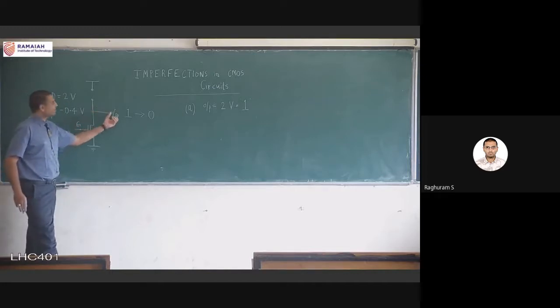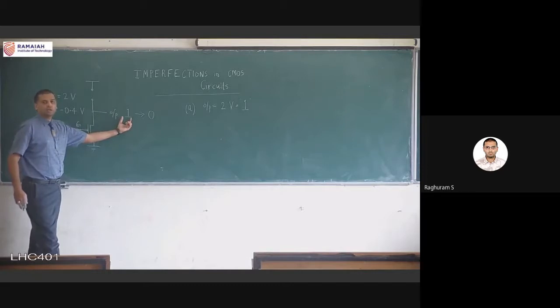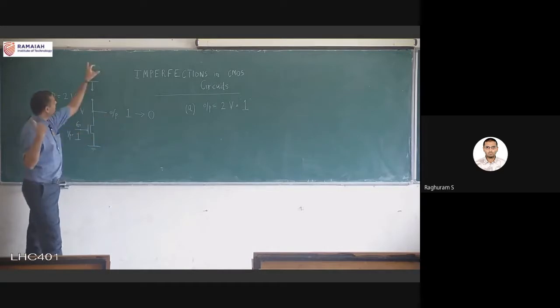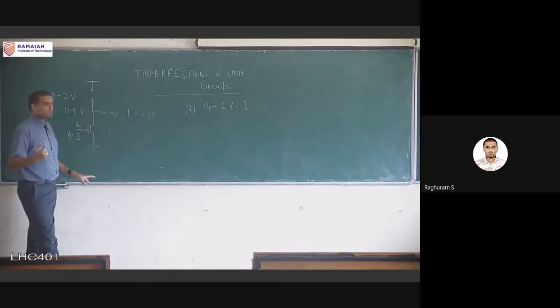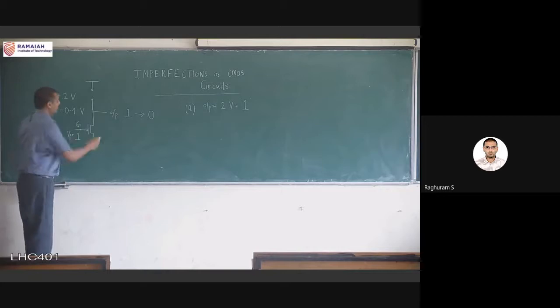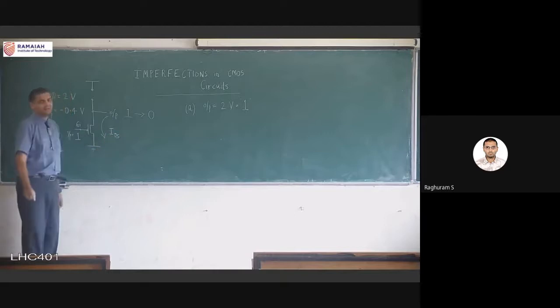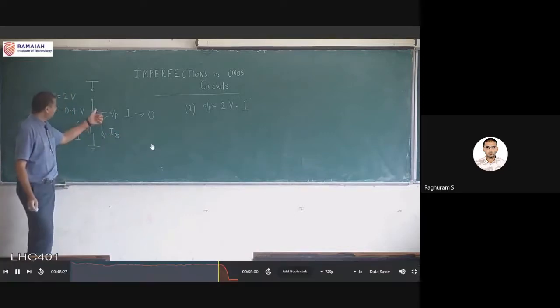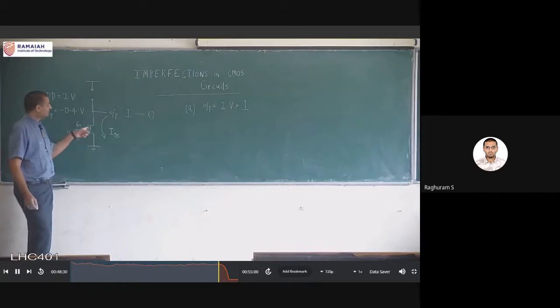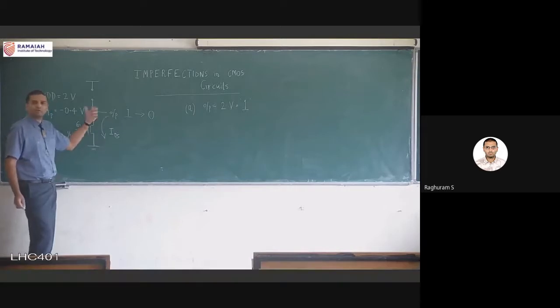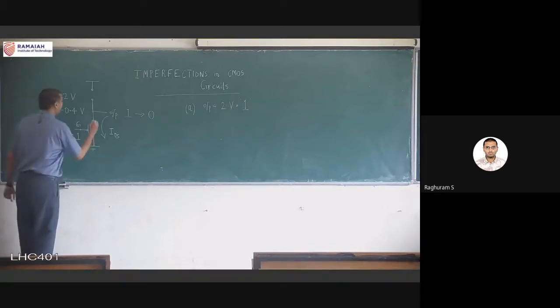That positive charge is corresponding to logic high or VDD, and that charge has to be removed, and it cannot be removed in this direction because this is an open circuit. So definitely the charge has to be removed in this direction, which means that the charge will flow like this, which means that is the current direction. Since the current direction is from top to bottom, the direction in which the holes have to move is the same direction, because this is the direction of positive current. Holes are carriers of positive charge, so they will also move from top to bottom.